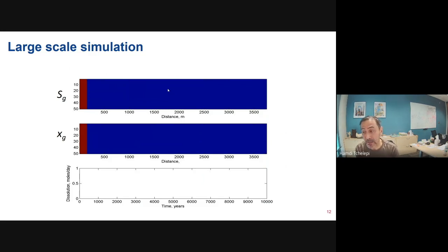It is not turbulent, so the Reynolds numbers here are very, very small. But the near chaotic nature of the early evolution of the fingers is as difficult to model as in turbulence, where you would miss the dynamics if you only do Reynolds averages without accounting for the instability. So it's a challenging problem.